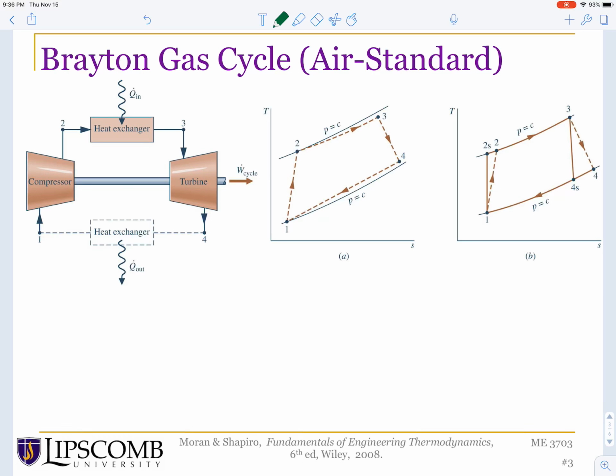Okay, and there are two ways we can represent some of the nasty irreversibilities in real life. One of those is with the heat exchangers. Those involve piping that carries the fluid, the air, and you're learning in your fluid mechanics class, air has viscosity. Viscosity of flowing air causes pressure drop, and that pressure drop robs us of useful mechanical energy